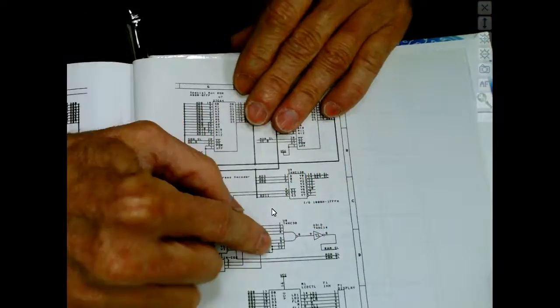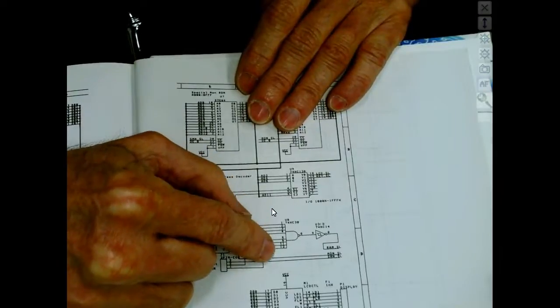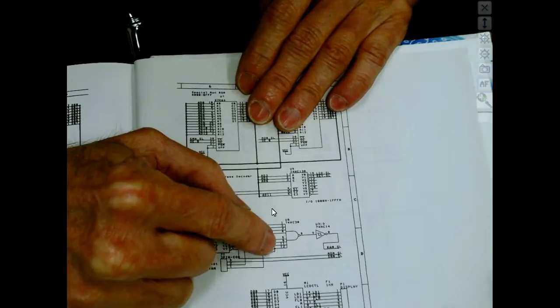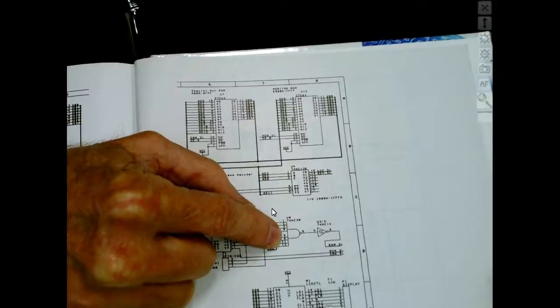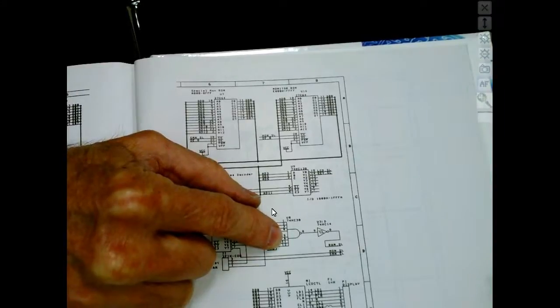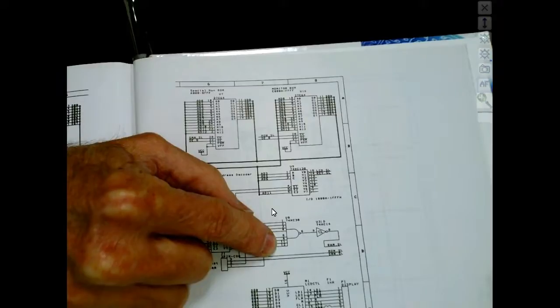The problem is, on these guys, what's a legal high? What do we consider to be a legal high? 2.4 volts and above, right? And what do we consider to be a legal low? About 400 millivolts. Between 400 millivolts and 2.4 volts, we don't know. It's going to switch somewhere, right? You understand? But we don't know where it's going to switch. We know we guarantee a switch if we put at least 2.4 volts on that input. We're guaranteed for it to switch. If we put less than 400 millivolts, it's guaranteed to switch.